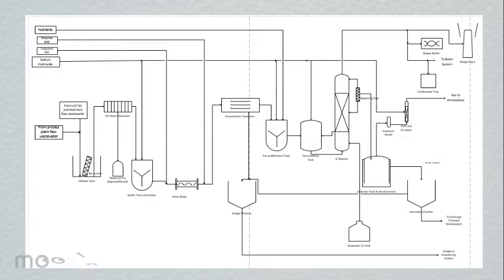In biogas treatment, the amount of biogas produced depends on the COD load applied to the IC reactors. The higher the COD load is, the higher the biogas production will be. The biogas will be collected in the degassing tank on top of the IC reactor for gas-water separation. The IC reactor and the biogas treatment facilities are a closed system. The biogas is burnt either in the process boiler system or the flare without emission to the surroundings.